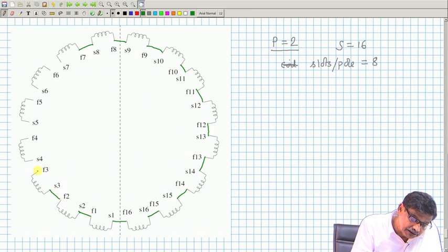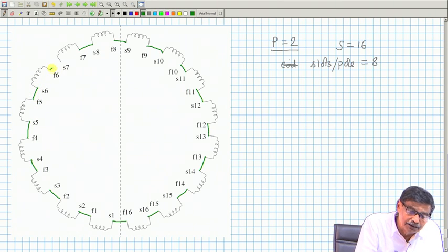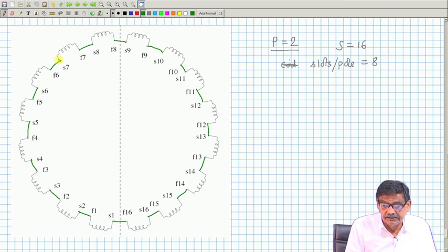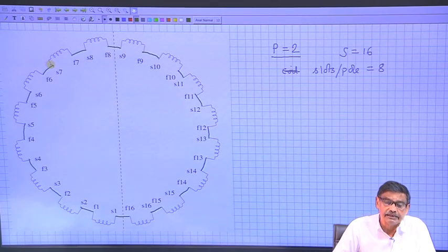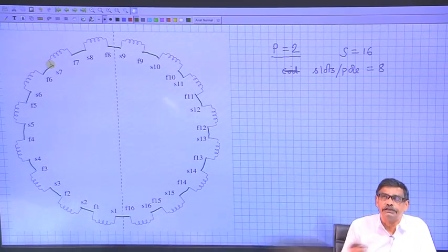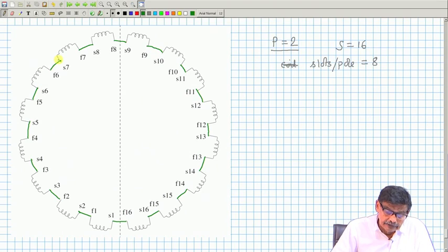So, these coils are connected in series. Will there be any circulating current? No, although each coil will become seat of EMF, because if I show the polarities of the voltages, as many plus minus voltages you will see in that series closed loop, so many minus plus you will see, they will cancel each other.